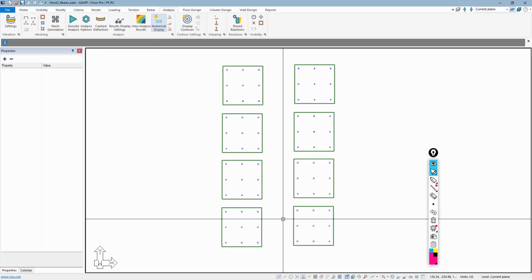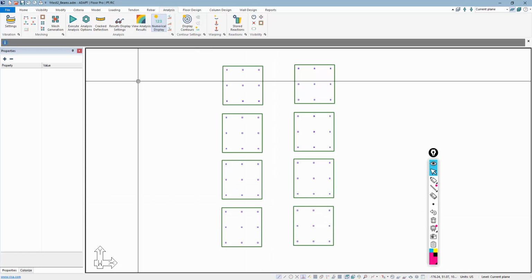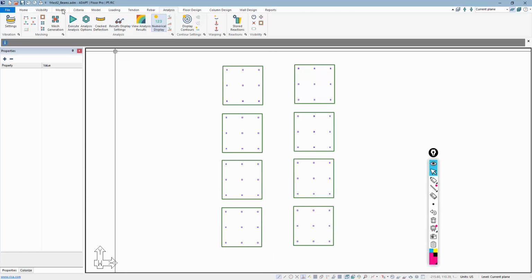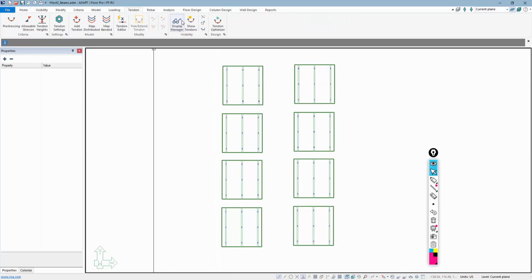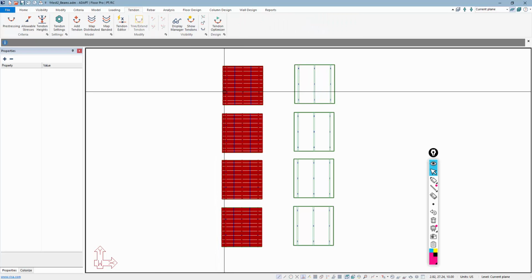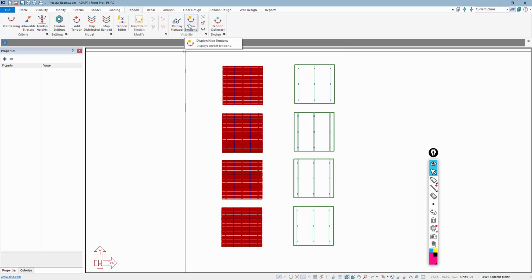The same type of approach can be used for a one-way slab with beams. In this example, we have beams in the model. Let's go ahead and turn those beams on. In view, we can see we have beams in the Y direction and then the one-way slab spanning in the X direction. And again, in the stack of columns on the left side, we have post-tensioning. So we have post-tension beams with one-way slabs, and then we have RC beams and one-way slabs on the other side.